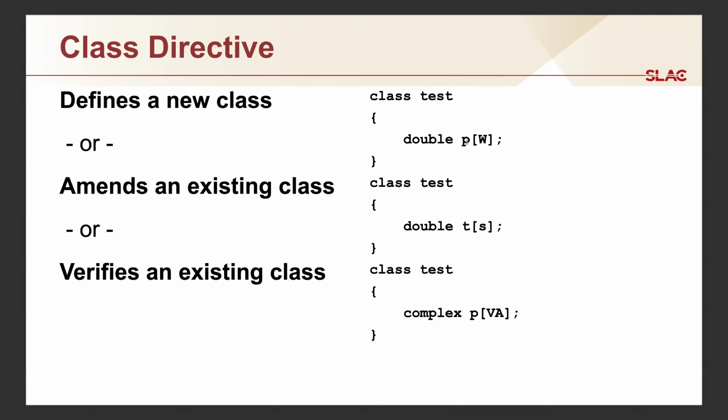Doubles and complex values can have units. Other properties cannot, but they may have other features such as enumerations and sets having keywords, for example. And that syntax for different property declarations is documented in the GridLAB-D documentation. But it's a pretty straightforward way of creating your own class that implements a bunch of properties, and then we'll talk about later how you implement methods in those classes.